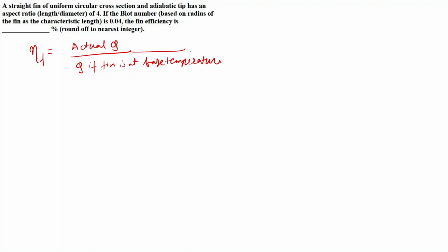Okay, so we define this fin efficiency as eta_f equal to the actual heat transferred upon Q if the heat transfer of the entire fin were at base temperature, that is, if the fin is at base temperature.